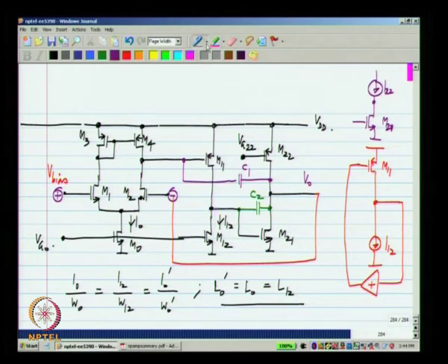So, we have a positive incremental gain amplifier connecting that way, and we know that if we do that, M21 is in a negative feedback and a current of I22 flows through that. Okay. So, if there is DC negative feedback around the entire op amp, each of these stages will be in feedback and everything will be biased correctly.